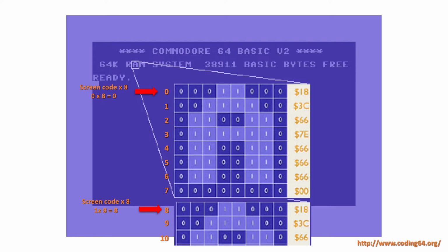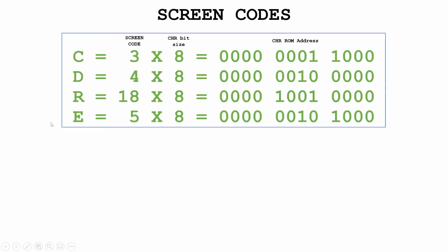Based on these new assumptions, let's try and revisit for a second the fault that this Commodore 64 has, which is the incorrect characters on screen. Now, previously I addressed that using data lines and assuming there was a stuck bit on the data lines, but again, we now assume that a data line may not be involved because of what I just said. So let's revisit everything, imagining that we may have an issue with addressing the characters rather than displaying the characters. Now, let's go back to our good characters on screen, which are C, D, R, and E.